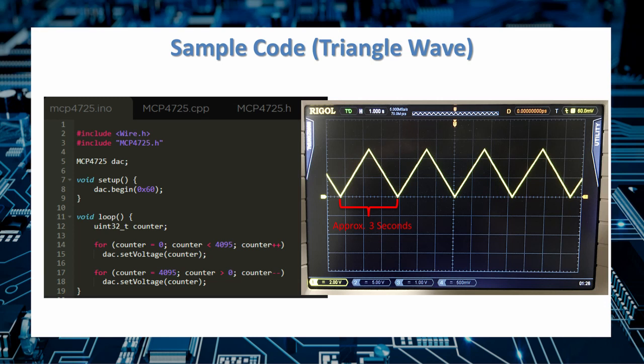This particular example also shows the limitations of using an I2C interface. Let's look at how many different operations and clock cycles it takes to put that out. First off, we run through about 8,200 writes, and for each of those writes, we've got to write out 4 8-bit words. So that's 32 bits that have to be written out, and then there's overhead, right? There's probably some information that goes out before and some information that goes afterward for handshaking. So let's assume 50 bits. We'll assume that we're writing 50 bits each time, and we're doing that 8,200 times. So that's about 400,000 cycles.